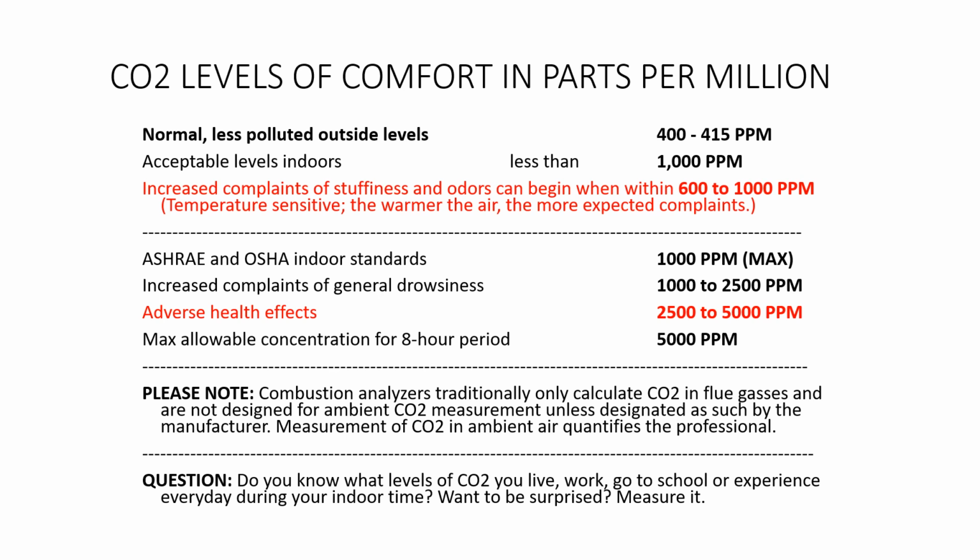But a lot of people will be in an enclosed space with the heater on, not realizing that it's stuffy, and their tiredness, their drowsiness is because their levels may be over 2,500 parts per million, and some of their poor health symptoms may be caused by that kind of stagnant air and too much rebreathing of their own CO2.